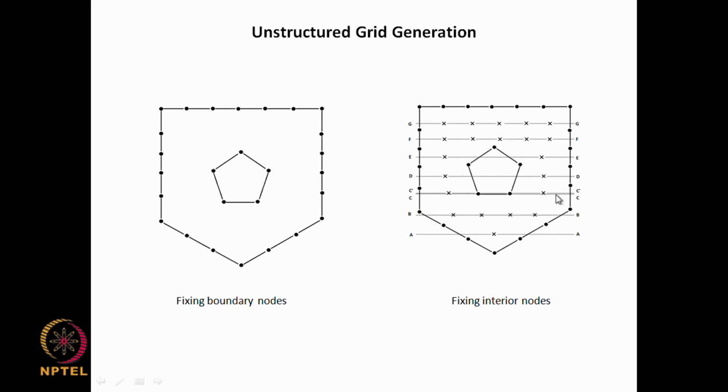so in such a case I can move it up or down slightly and then put the points here. So, in a case where I feel that the points are very close to existing points, then I can move the points up or down, because I know that it is not possible to get exactly the same length L all the time. It is okay to have sometimes maybe 0.7 L distance or 1.3 L distance. So, accordingly we have to move the interior points around after using this general guideline to place them inside. Okay. So, this is one simple way for a 2D case of fixing this kind of domain.